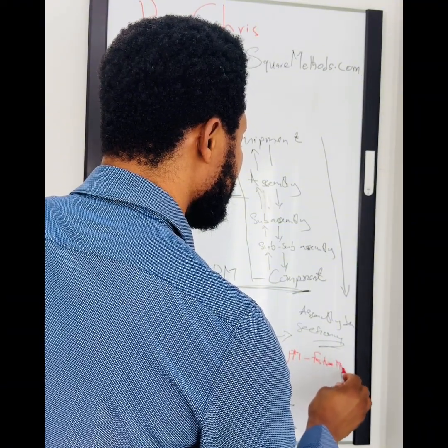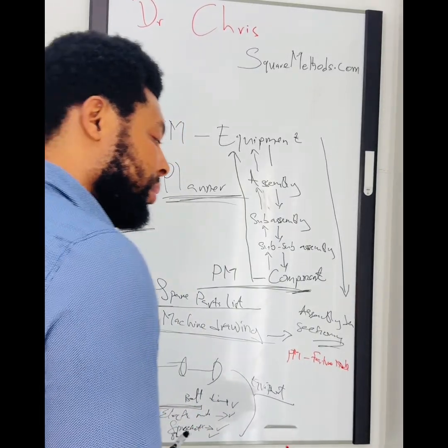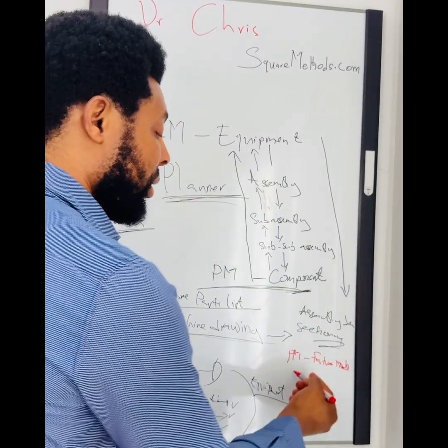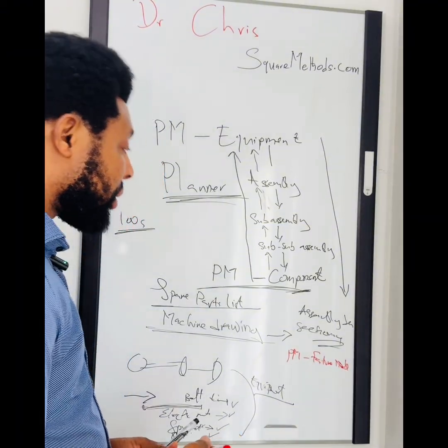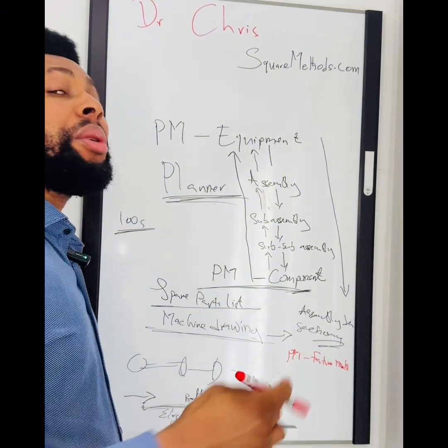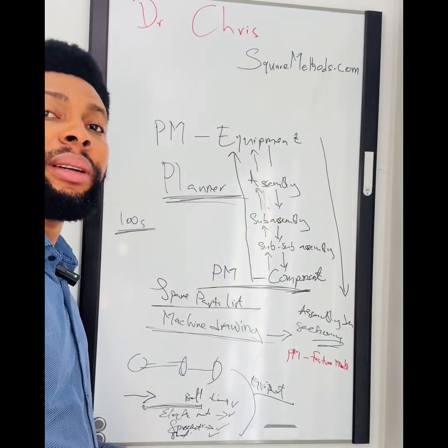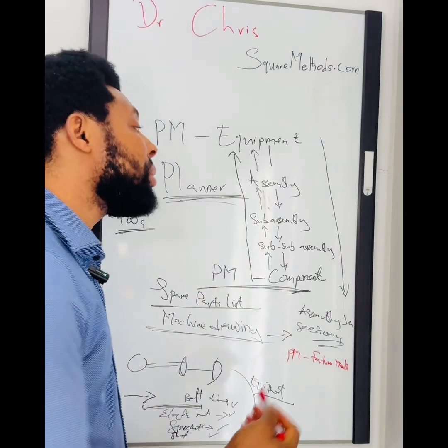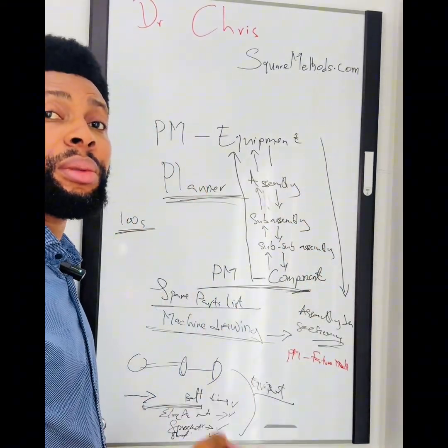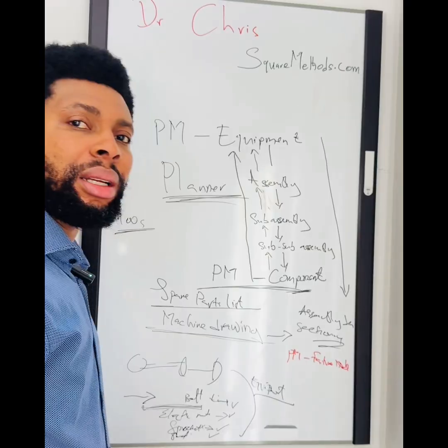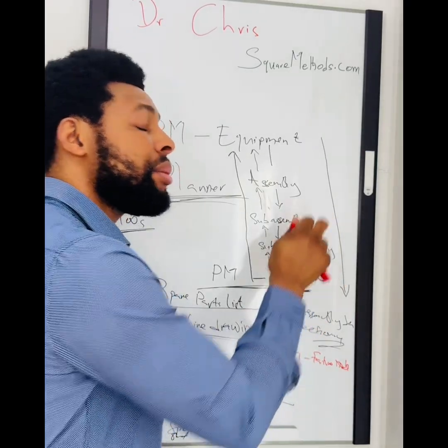And I already defined to you that failure mode refers to components and how they can fail. You get it, right? So if you want to learn how to maintain a machine, the first thing to do is to break the machine down into subsections, into a hierarchy. Then from there, you can define maintenance for each component.